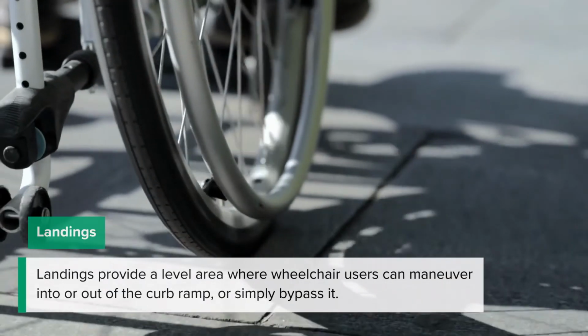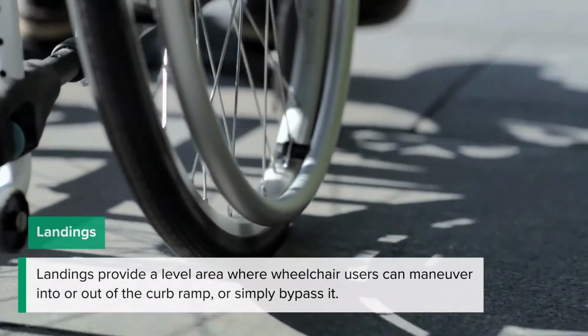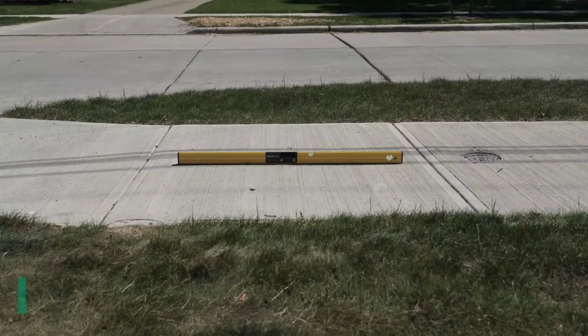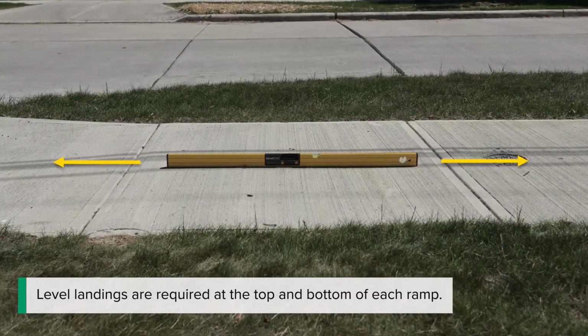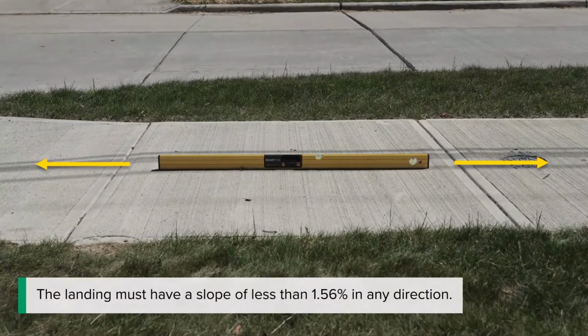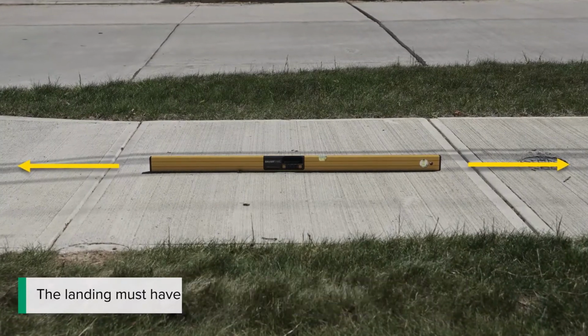Landings provide a level area where wheelchair users can maneuver into or out of the curb ramp, or simply bypass it. A level landing 5 feet square is preferred. Level landings are required at the top and bottom of each ramp. The landing must have a slope of less than 1.56% in any direction.